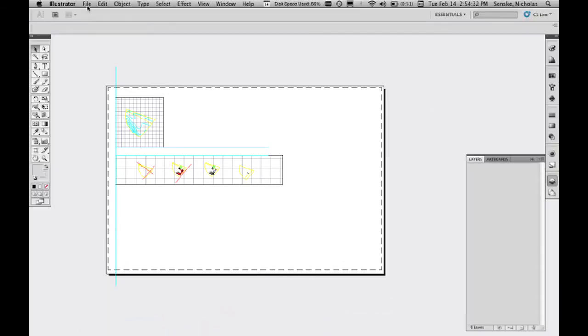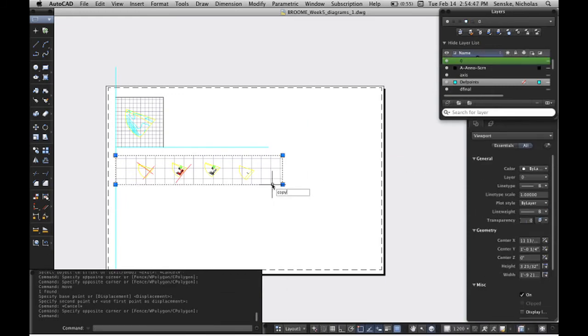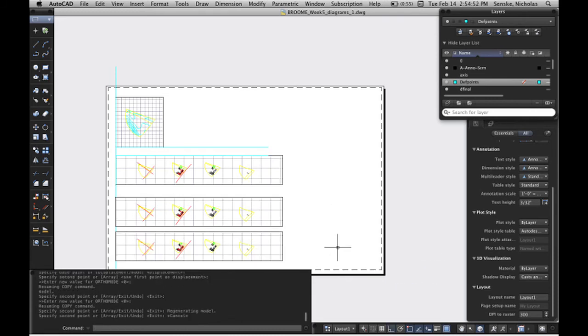Open up. One question real quick? Yeah, sure. So when you make new viewports, or whatever we're calling those windows, and you copy it, are you actually copying what's in there? If we made that again down there, are you copying the model space too? No, this is the thing, it's just a magic portal into model space. It's not making literally a copy of it. It's just another view into that. So if you change something in one of those diagrams, it will change in all of them. Yeah, it's just a magic portal. Got it. Yeah, that's the beauty of it.